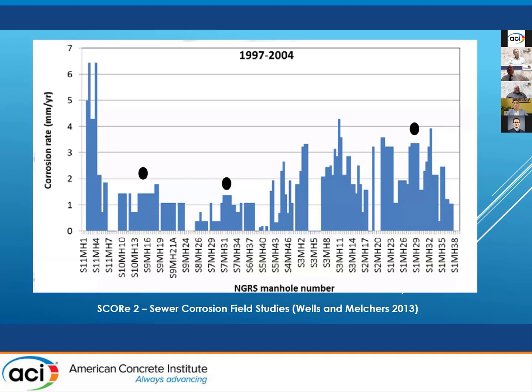And that's one of the reasons why I think that having more microbially induced corrosion resistant concrete to just improve these deterioration parameters, rather than very expensive linings through the whole system, is probably a very economic way to go.